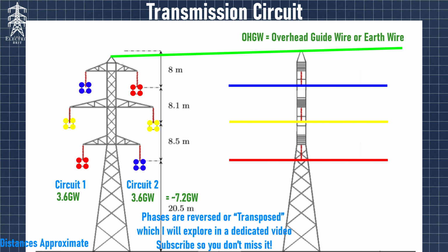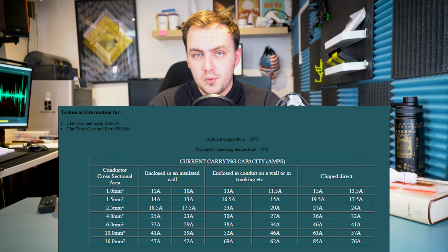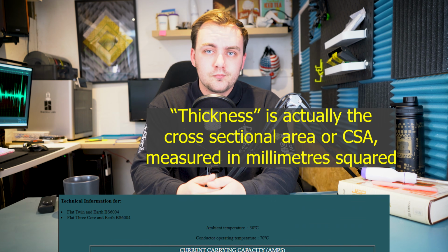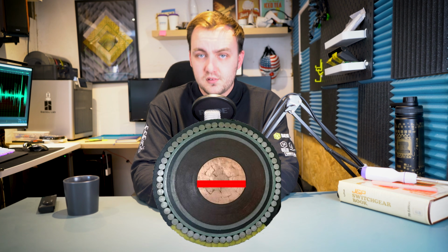Now let's talk about why high current, not voltage, becomes the limiting factor for cables. So you might have heard that higher voltages are more efficient at transporting large amounts of electricity, or that certain cables aren't thick enough for high levels of current, such as in your home. Both of these are correct, and in the simplest terms, higher current requires thicker conductors, which are heavier and more costly, and so are less desirable.